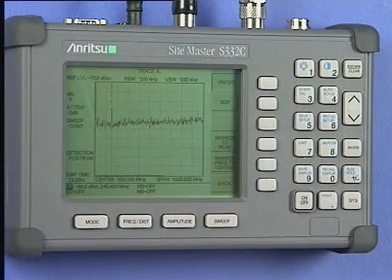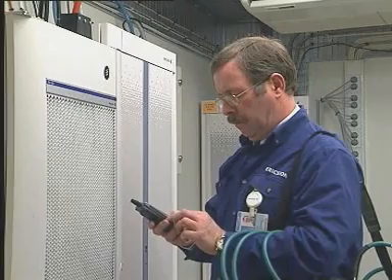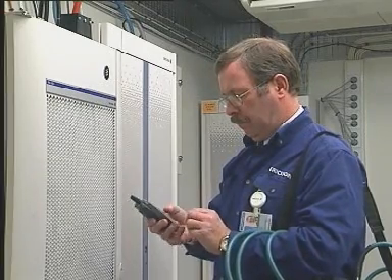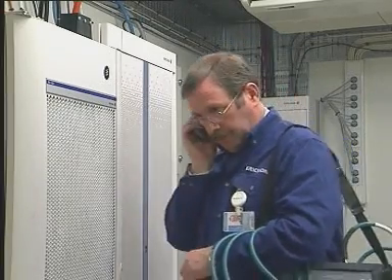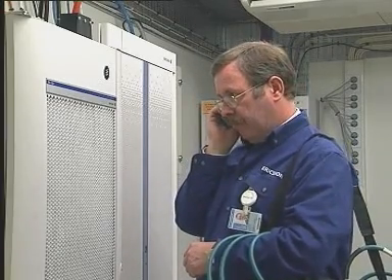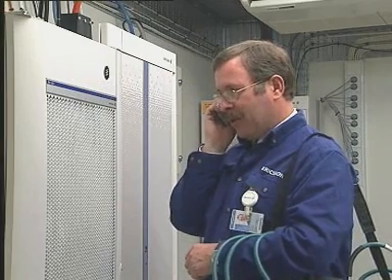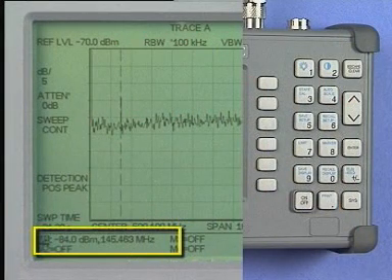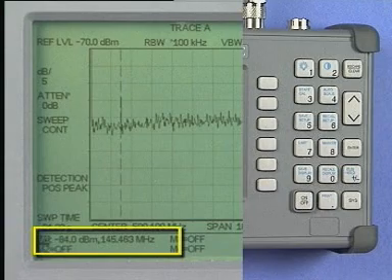If you have an external carrier that is interfering with the radio system, then you will need to call in the cavalry, since other equipment will be needed to locate the source of the offending signal. In many cases, only the frequency of the offending signal will give us a clue as to its source. In our example here, we see a carrier at 145.5 MHz, which just happens to be in the upper half of the 2-meter amateur radio band. In this case, a visual search of the area for ham radio antennas may possibly be sufficient to locate the source.